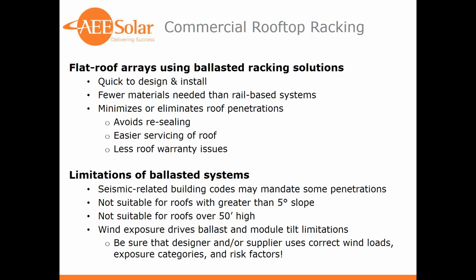We're seeing that fewer materials are needed for ballasted systems. And most importantly to some roof owners, with your TPO roofs, it minimizes or eliminates the needs for roof penetration. So you don't have to seal them, easier servicing the roof if there's ever an issue, and we see overall less warranty issues of the life of the PV array.